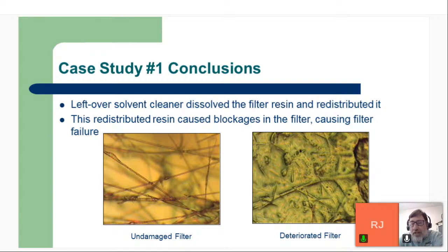Yeah, Richard, and I was called in on this one because this particular customer was really baffled by a filter system where shortly after they would install a brand new filter, it would go right out on DP. They couldn't get any flow through the filter, and we saw this effect and didn't know quite what to make of it until I got on site and talked to the mechanic who was in charge of changing out the filters, and he communicated that he was using brake cleaner and spraying the inside of the filter housing to help clean it out.